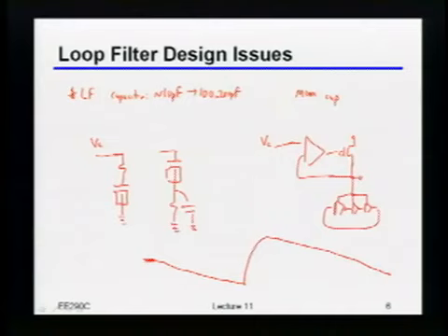And in fact, you can imagine that, let's say I wanted a really big multiplication ratio, meaning my VCO is running at a much, much higher frequency than the reference. This can get really bad, right? Because I could just be integrating that leakage like forever, okay? So indeed, in some of the more modern technologies, people actually moved to building this out of metal capacitors or some thick oxide or something like that. Maybe now if you get high-K dielectrics, maybe you can go back to the normal MOS capacitors, but definitely something to be aware of.